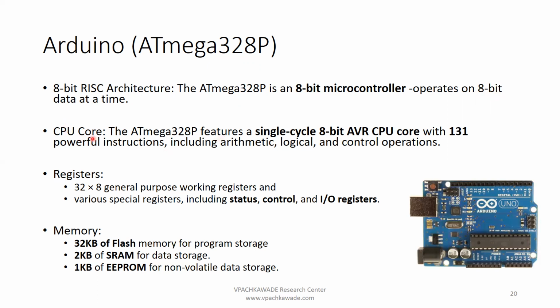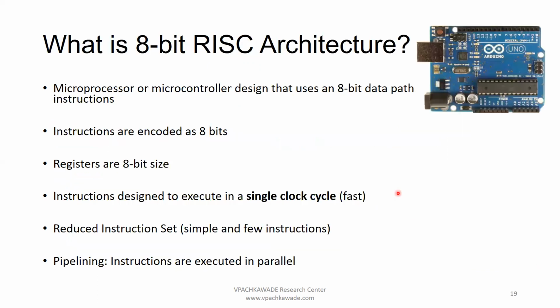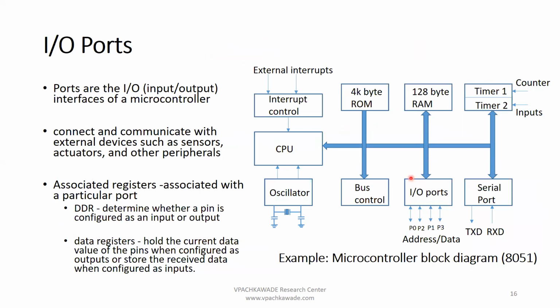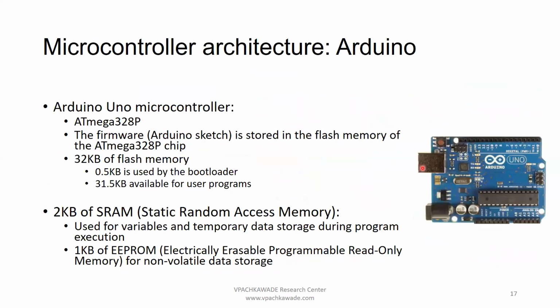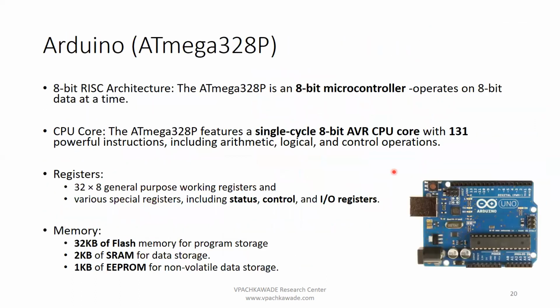Now that's the CPU. Remember, inside this chip, we have this kind of architecture, which we have covered in the previous module. Inside the chip, you have the CPU, the interrupt control section, memories, RAM, ROM, input-output ports, and unidirectional or bidirectional address and data buses, all operating at 8 bits. So we come back to our slide.